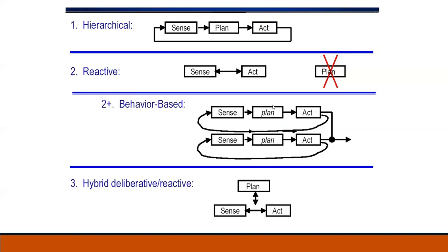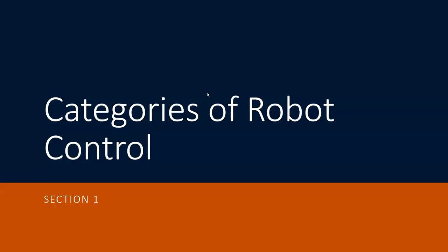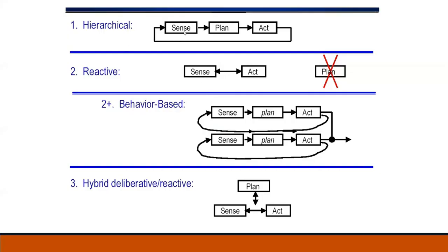And then this actually is the environment, but for the real control scheme, there are four kinds of control scheme: hierarchical, reactive, behavior-based, and hybrid. Four kinds. Hierarchical is the most general one: sense, plan, and act. But hierarchical has a big problem, right? What is the hierarchical big problem? This sense, plan, and act method.